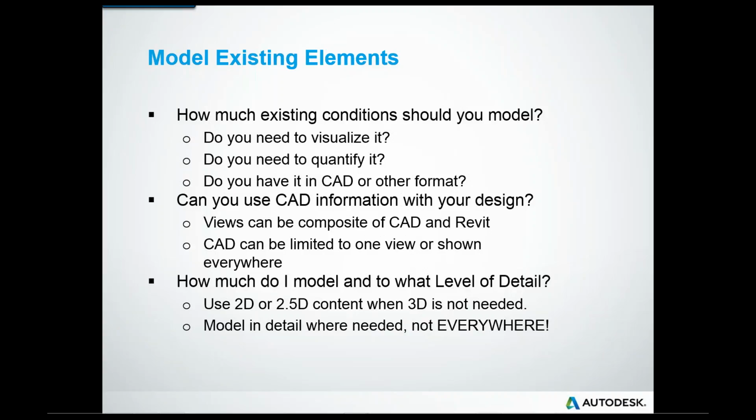So for example, if I were to do a wall section and do a call out of that wall section, I would just do a blow up detail of that wall section or a parapet, and information would be provided there, and I wouldn't model it everywhere. And that is basically where you would draw the line.